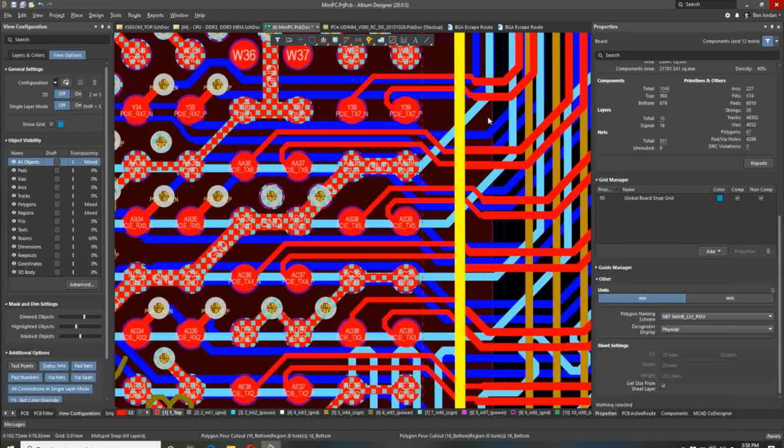And this is really... Rooms were invented for controlling component placement, but they've evolved to support many other useful things for routing too, like necking out of a BGA is probably the primary use for rooms today, way and above more than component placement. How does that look in design rules?